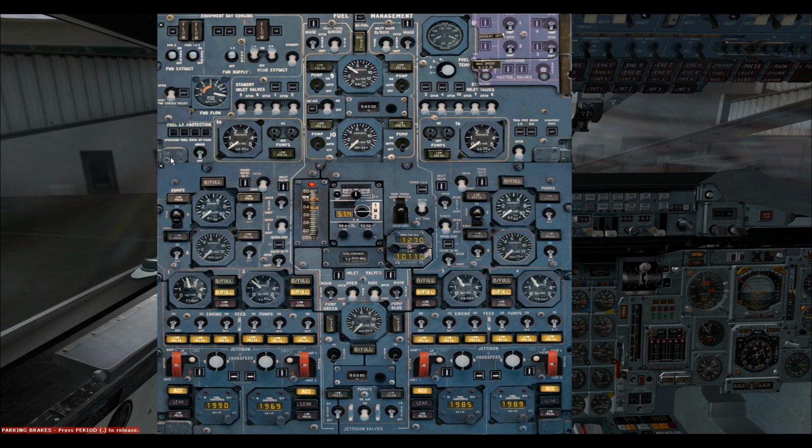If you're going to do a complete shutdown and I still have ground power, you would then turn off your equipment bay cooling, but I'm just going to leave that on for now. So that's it. We've completed our flight. So stay tuned for the next section where we'll talk about the Barbados loadout and also recovering from mistakes.